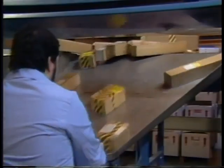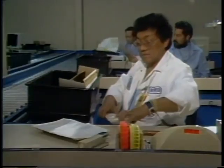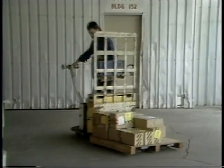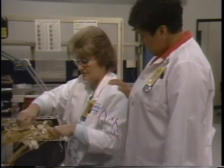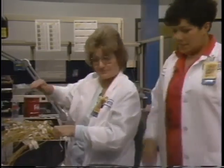ESD awareness is critical to everyone who handles ESD-sensitive hardware. ESD control exists in all areas: receiving, stockrooms, kitting, assembly, inspection, test, and shipping. Each of these areas are subject to customer audit. You are the key to eliminating ESD damage. Your shoes, hands, or other body surfaces can generate and store charges. The best way to control ESD is to make sure you always wear the wrist strap and leg strap when you are handling ESD-sensitive hardware.